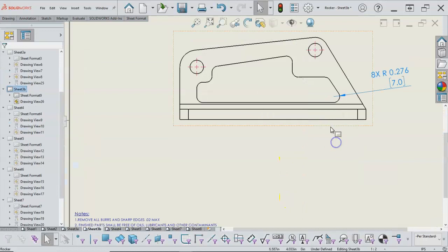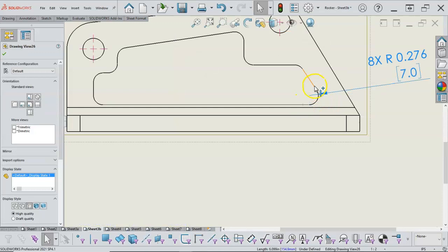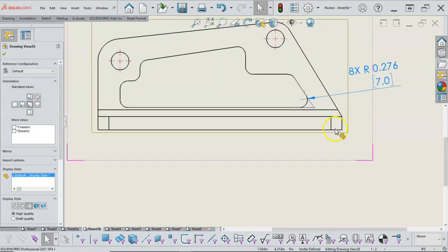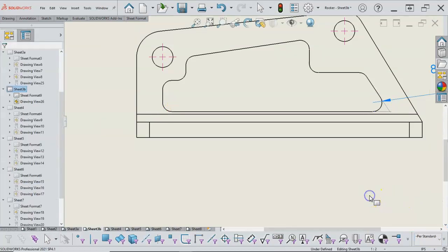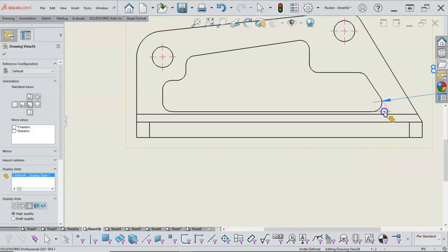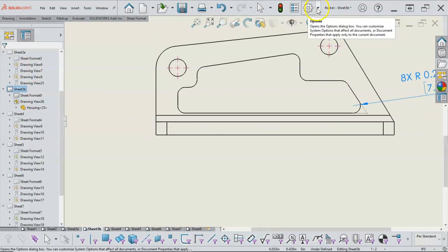Okay, so the intent for the virtual sharp is to select and control select a line, hit the S key, and place the point. That gives me the virtual sharp. And we switched out of per standard, so I'm not sure when that happened. Oh, and since it's on per standard, okay, so that's what it's cycling through, much like it goes to the property manager when it needs to go to the property manager. So that being the case,